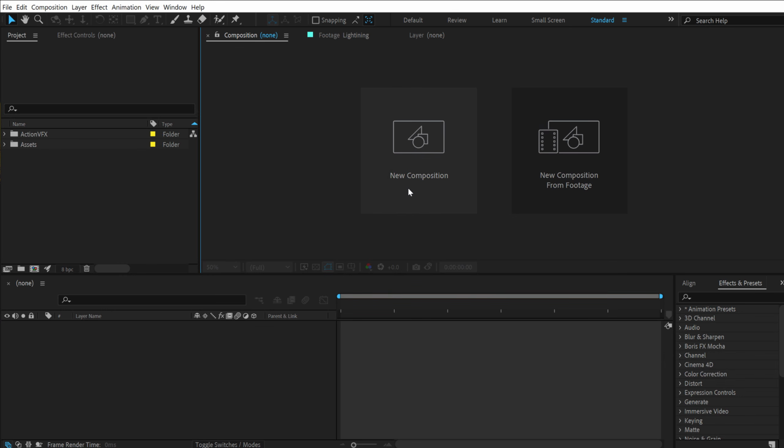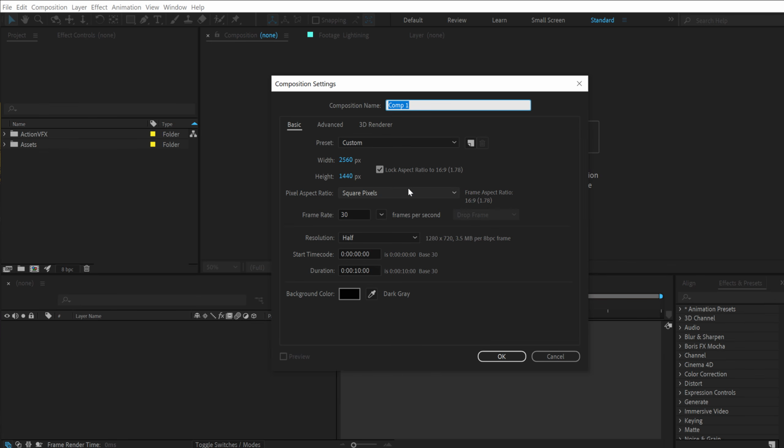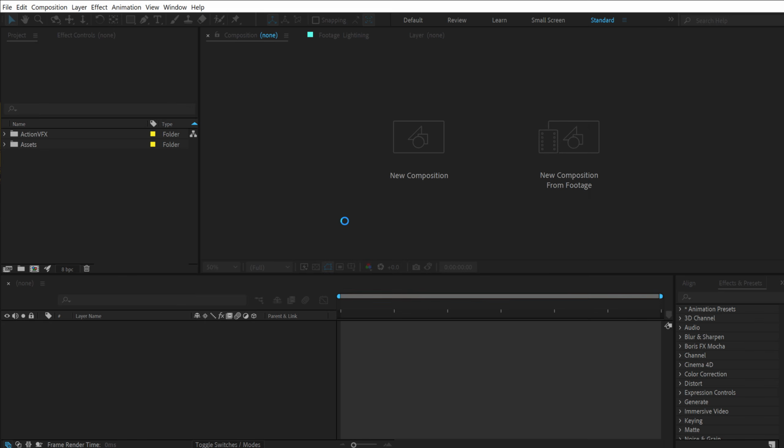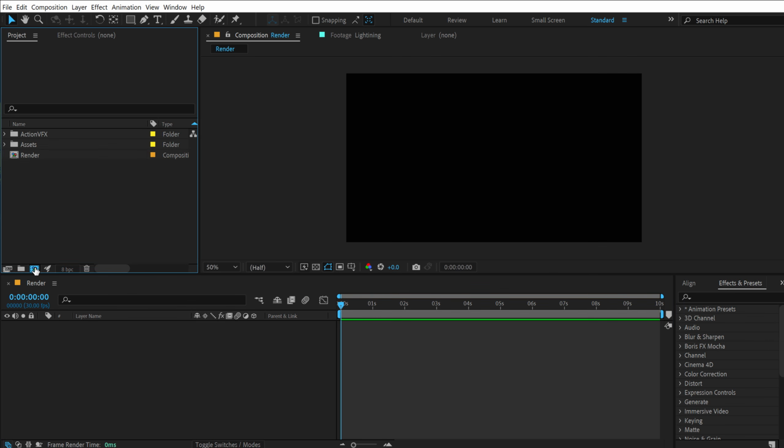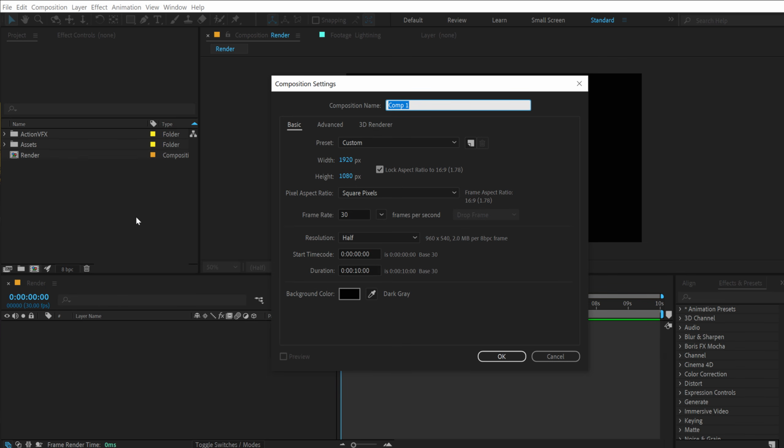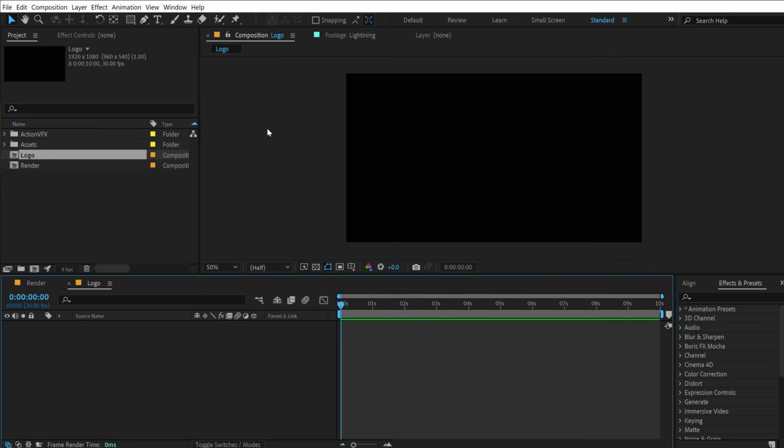Let's start by creating a new composition. Let's call this render, our main render comp. Let's go with 1920 by 1080, that is full HD, 30 fps and 10 seconds long duration. Press OK. Then create another new composition for our logo. So let's call this logo with the same exact properties and click OK.